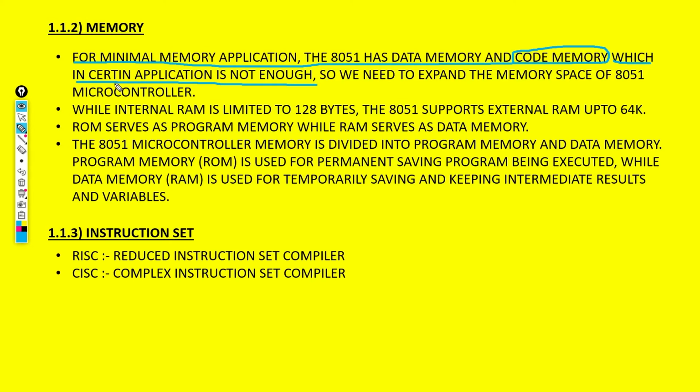As I told you, the 8-bit microcontroller has a little bit of disadvantage when it comes to larger data, because its memory is limited. Its RAM was only 128 bytes, so we will face problems when saving our data. But we have a solution for that.